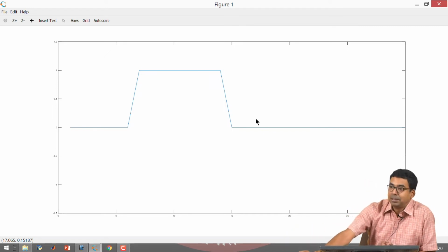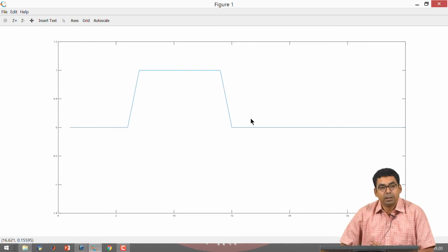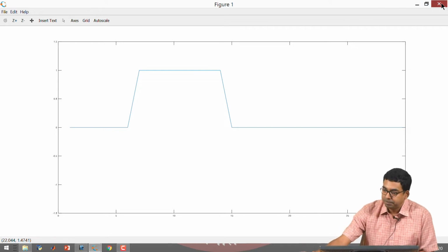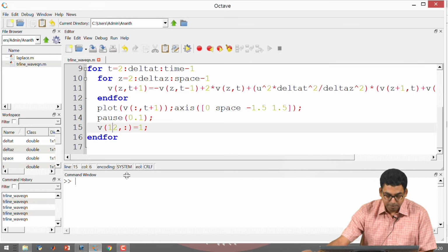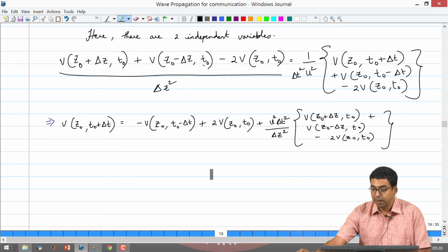Now, this needs a little bit more care, and it tells us that we have to look at transmission lines in terms of reflections. We have to understand in steady state what is going to be the voltage in transmission line, alright. We also need to understand, if you detect a 0 volt in transmission line, does it mean it is really carrying 0 volt, or does it mean that there is a forward voltage and a backward voltage superposed that is giving you 0 volts. All these things have to be considered in great detail, alright. But this is a good starting point, alright, because I have touched the word reflection. Now, we will go back and look at what all we have done and where we are getting, alright.